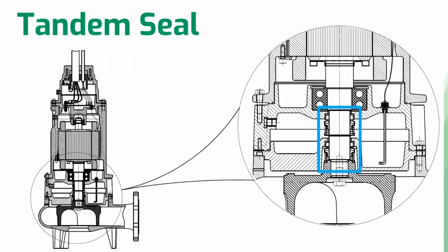So right here, that is where the seals are going to be located. You can see that bottom seal between that impeller and the first section of that housing. So if that seal does fail, water will fill up, and that moisture probe, which is that rod on the right, will detect that there is a seal failure and notify you.